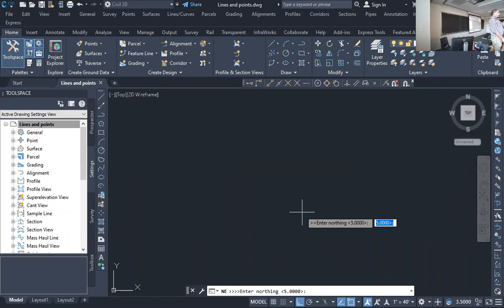Be careful. In CAD, when you tell it to draw a line, it's X comma Y. This is asking for northern, which is your Y coordinate first. Okay. So for Centennial, it's 507,214.45. Now it's asking for the easting, 2,673,119.33.